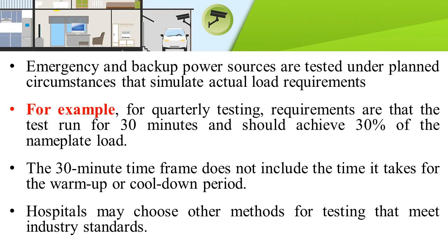For example, for quarterly testing, the test runs for 30 minutes and should achieve 30% of the nameplate load. The 30-minute time frame doesn't include the time it takes for the warm-up or cool-down periods. Hospitals may choose other methods for testing that meet industry standards.